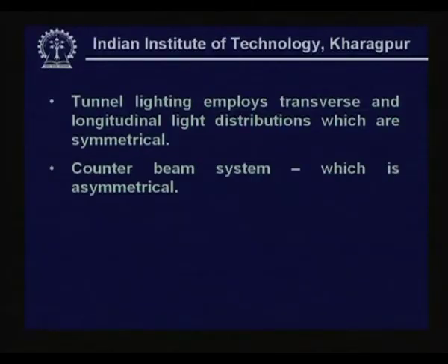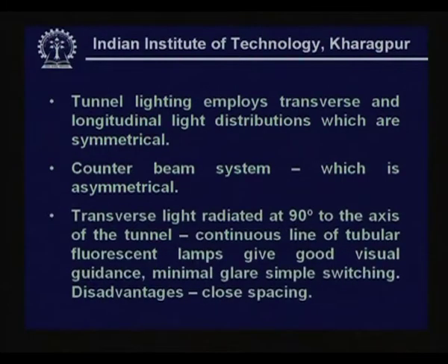Counter beam system also is used, but that produces what we call asymmetrical lighting. Transverse light is radiated at 90 degrees to the axis of the tunnel.